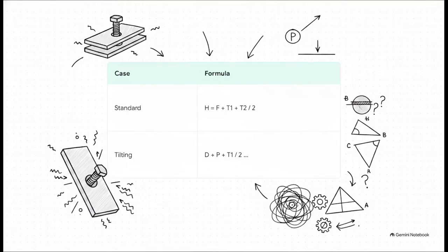And hey, if you need the cold, hard mathematical proof, ASME Y14.5 lays it all out right in non-mandatory Appendix B. The standard fixed fastener clearance hole formula is actually pretty straightforward. But, and this is a massive but, the standard explicitly states that this simple formula completely fails to give you enough clearance if your threaded holes are out of square. If you don't use a projected zone, you are forced to use the nightmare tilting axis formula. And trust me, that requires factoring in depth of engagement, maximum projection, and enough trigonometric headaches to make you rethink your career choices just to size a simple clearance hole. Using the projected zone symbol just keeps your math simple, and more importantly, it keeps your assembly safe.